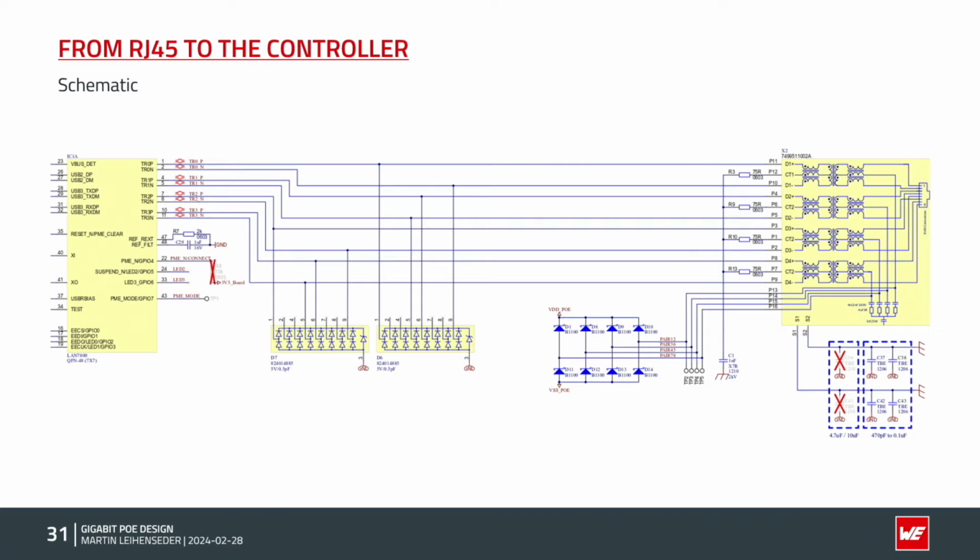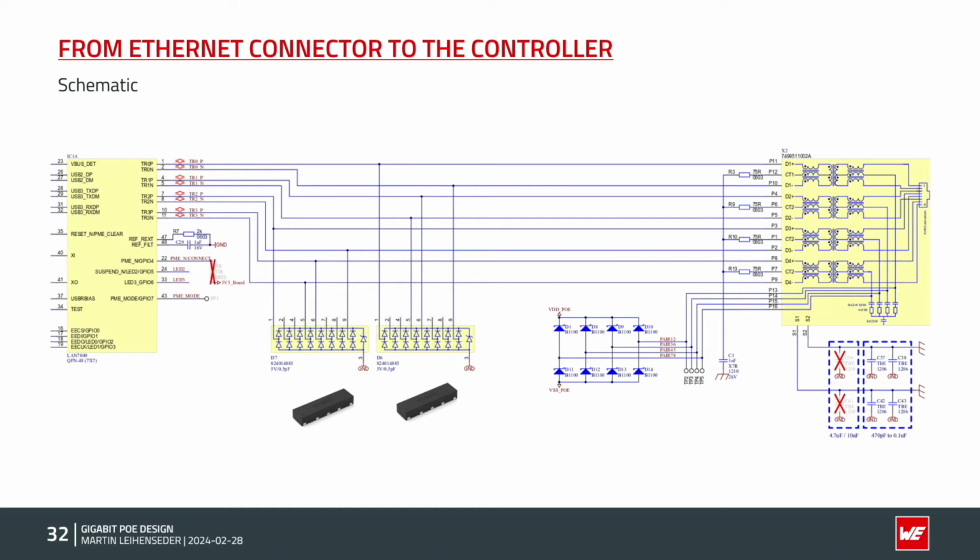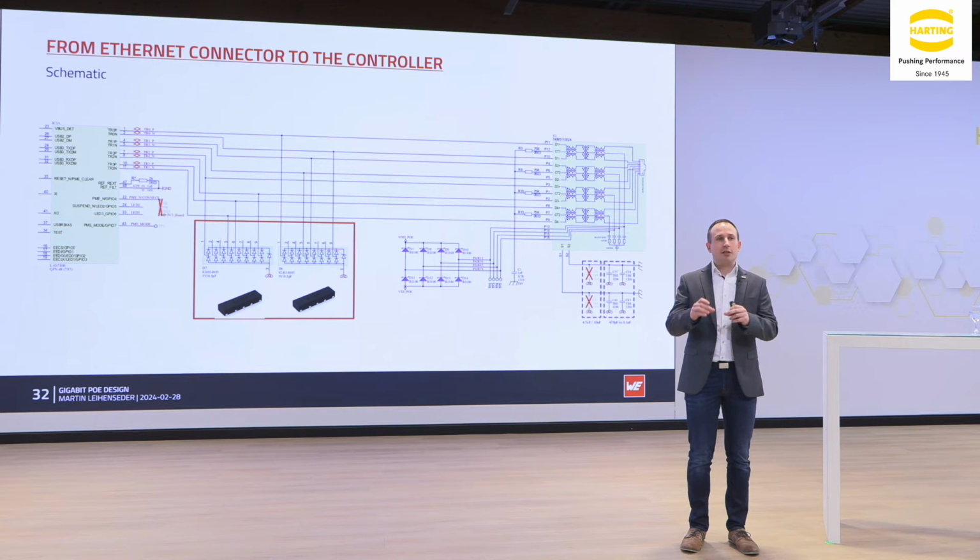First of all, on the right side, this is the LAN transformer. On the left side, this is the Ethernet controller. And here we have TVS diodes. This is needed also for transients coming over the cable, to reduce those transients. In our application, in our reference design, you can see not all ports are used. The reason for this is it's easier to design. So we took 2 of those parts, and so we did not need to route so much.